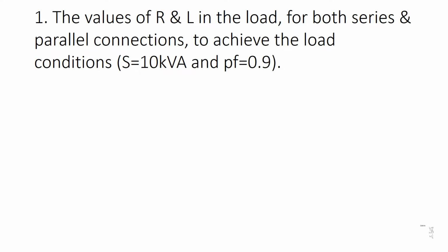Lagging means we have an inductive load. So when you are given a load consisting of R and L, you should understand this power factor is lagging, and you have to find the value of R using the active power values and the value of L using the reactive power values.